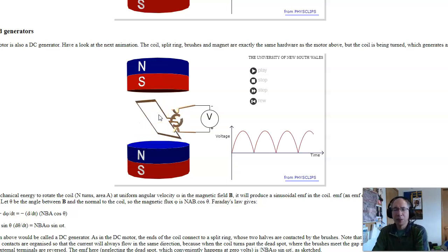That spark will jam AM radio stations, so likewise DC motors have to have thick metal casings to keep the RF interference out, otherwise you jam all AM radio stations, and the FCC gets mad at you. So DC motors are extremely large, bulky. Part of the reason we want to use AC motors.